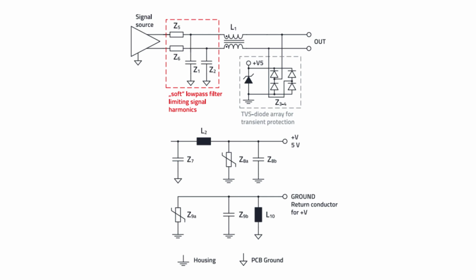The resistors, our Z5 and Z6, especially 3.3 ohms, are typically used for reflection damping and filtering in conjunction with the capacitors, our Z1 and Z2, and they're there to improve signal integrity and reduce interference. RF suitable types with a small body size should probably be used here.